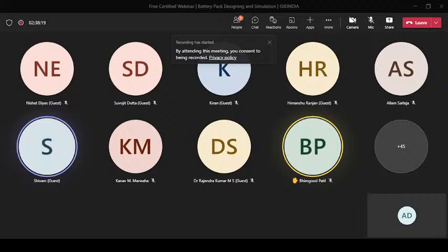I have already given you this example with the SOC. That means one SOC is 100% and another SOC is 80%. So what will happen when your 10 Ah battery pack is completely discharged? Your BMS will cut off the power from that battery pack, and you will get the signal that you have drained the complete energy from the battery.